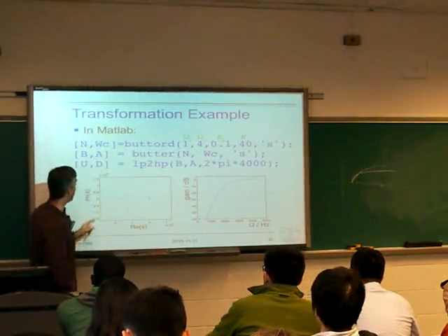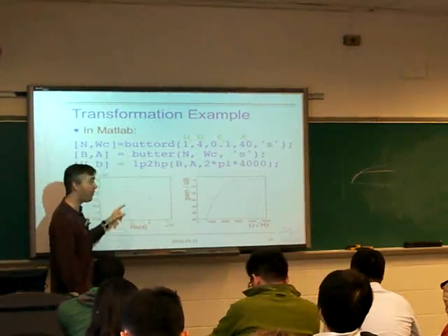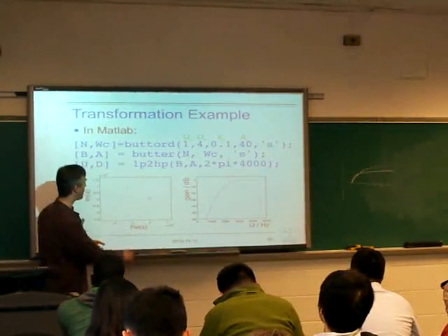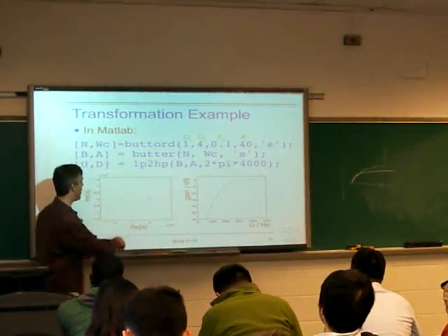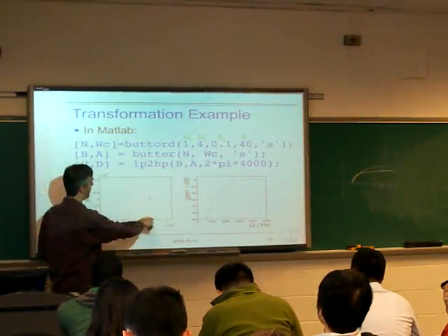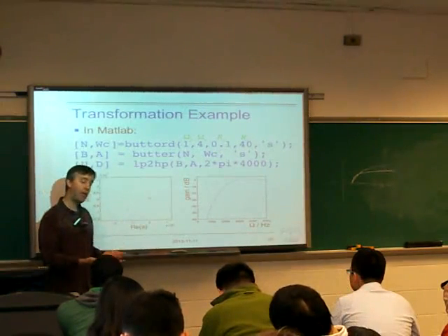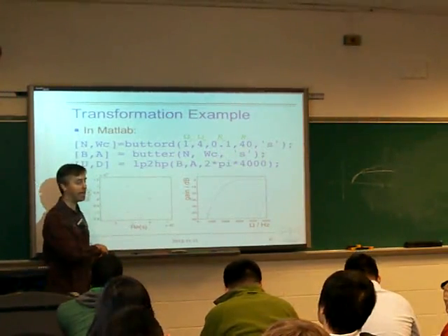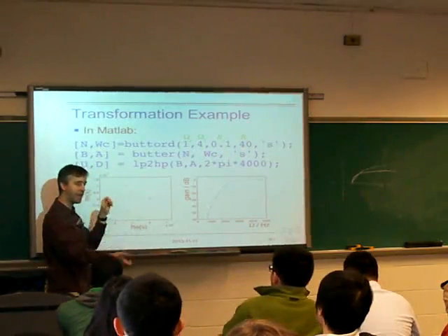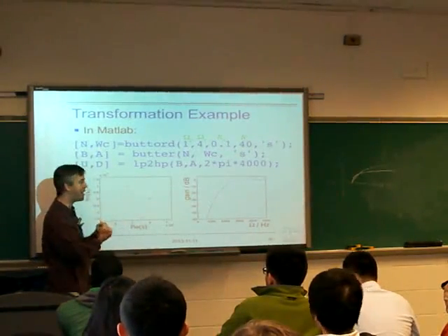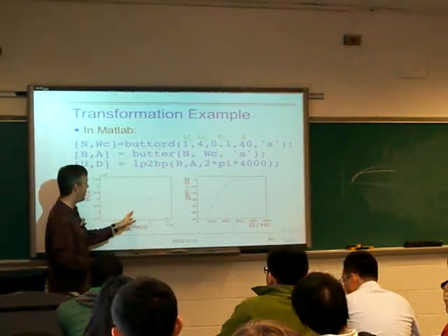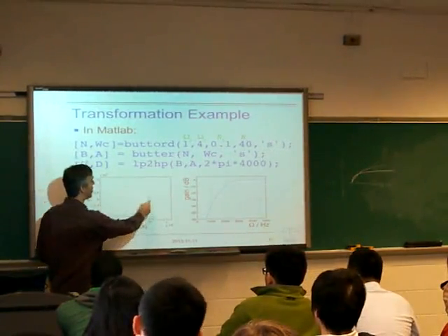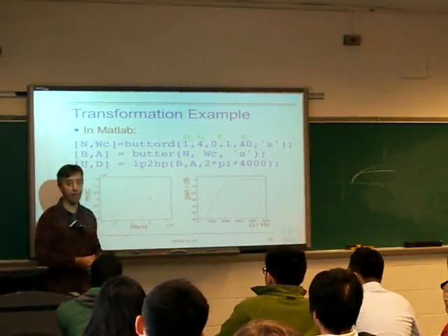Now, here's the result of doing this for this particular example. And here are the pole-zero diagrams. What's cute about this Butterworth high-pass filter is the poles are still on this semicircle. The actual poles stayed at a similar place. The semicircle may have changed in radius because omega p may have changed, but basically they're still in the same pattern. All that's changed is we've added n zeros here.